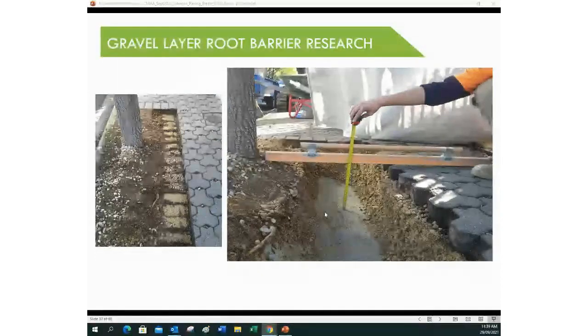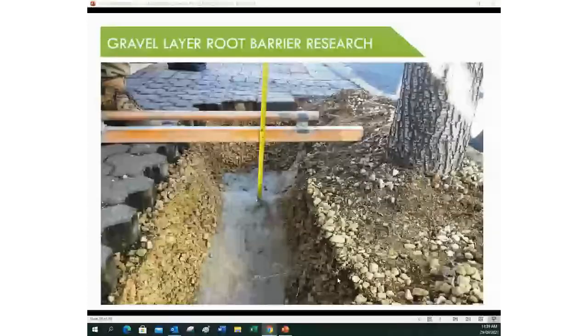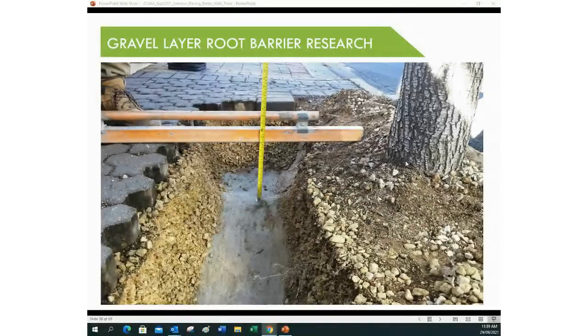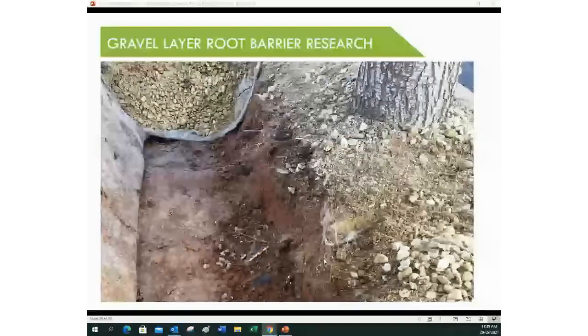We've still got massive clearance beneath the pavement surface, 80 millimetre brick. I think that's about 150 of gravel plus 30 to 50 of fines on top. So nearly 200 millimetres clear with no roots in there whatsoever. You can actually read the scale there. To the top of the pavement's 260, so 180 clearance. You can see a bit of a bulge in the geotextile there, right next to the tree. That is this large tree root. Instead of growing horizontally, business as usual case, they grow vertically down.